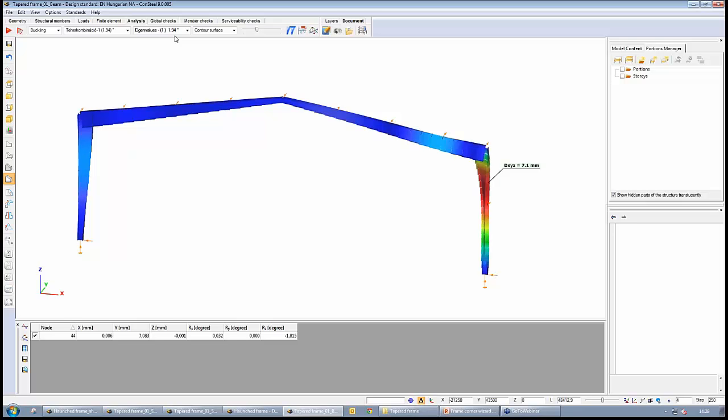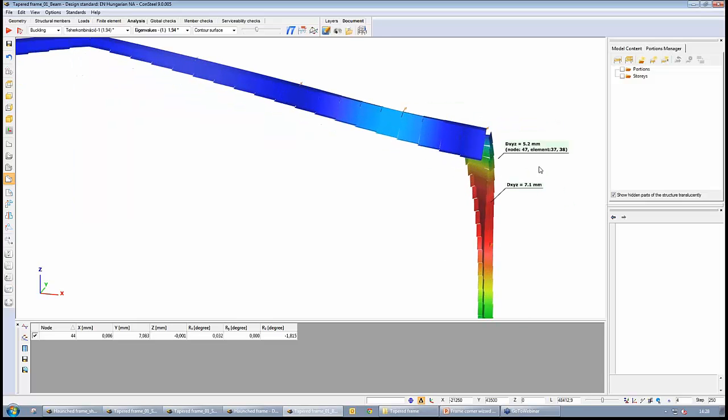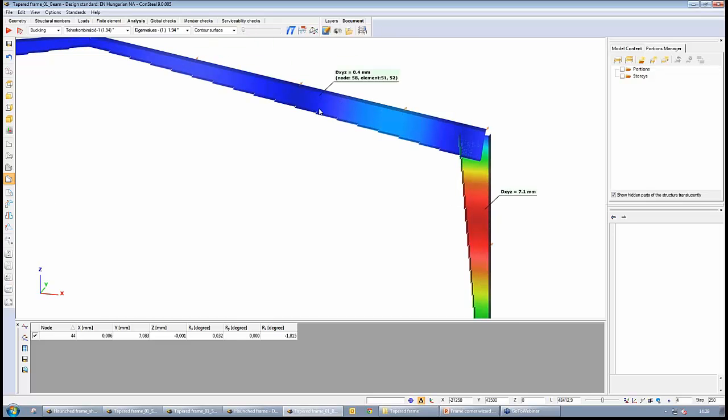So what is the reason for this? There can be many reasons, of course, but the basic reason is that if we see, for example, this hinged frame, the real connection, what are the most dominant parts now for lateral torsional buckling? The most dominant parts are the inside, so the lower flange and the inside flange of the column.